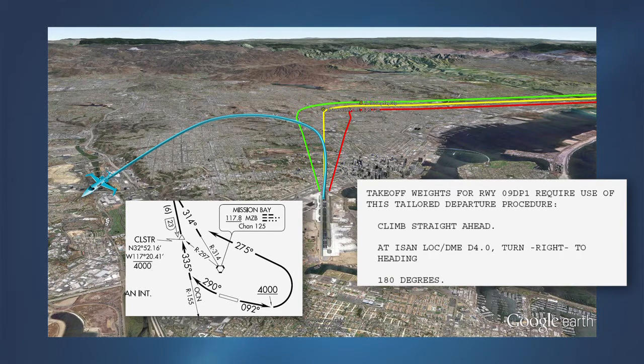On the other hand, if the engine fails after attaining 4,000 feet and in the left turn, the engine failure procedure is no longer applicable. At this point, though, the airplane is above the immediate surrounding terrain. The pilot has any number of good options available. However, it might be wise to think about these options as part of your pre-departure planning. Here are some strategies you may consider applying when the IFR departure differs from the engine failure procedure, or when you expect ATC to provide vectors after takeoff.